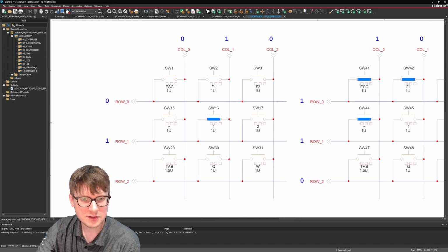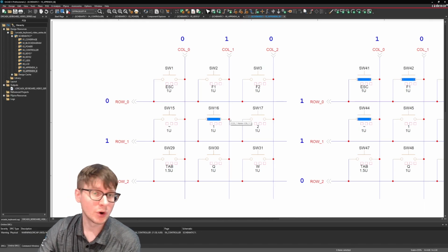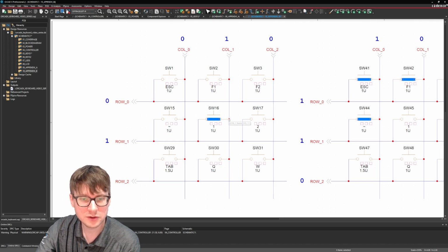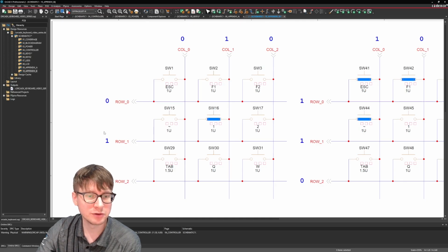So essentially that signal 1 or true or on, whatever you want to call it, 3.3 volts, travels through this connector to this wire and then gets output on this row 1 input. So if we press switch 16 and we only toggle the first column, then we will see that only row 1 will see an input value of 1.